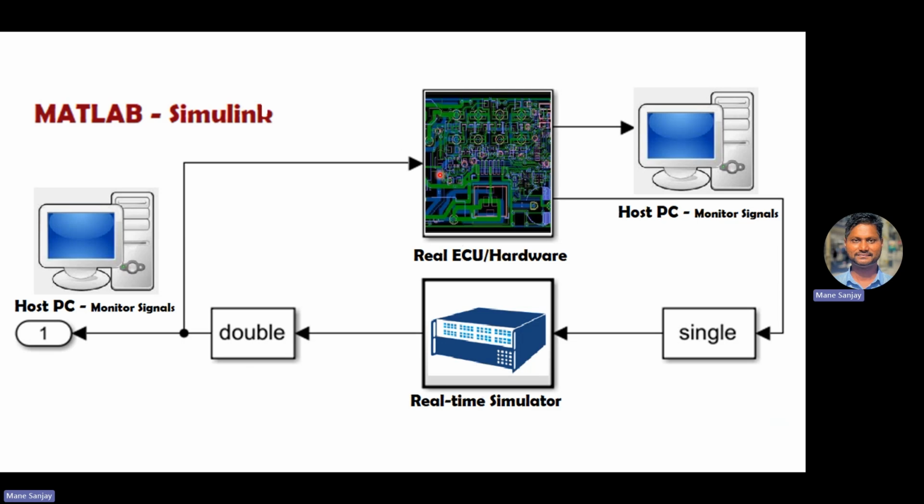When it comes to checking the entire logic which is written inside any of the ECU, then we usually use the model in loop simulation technique. And when it comes to real-time performance, we usually prefer the hardware in loop simulation. This method is basically used before production of that specific component. In terms of fidelity, HIL is very high fidelity, very accurate in giving the real-time behavior of the performance of the ECU or the model which we are simulating here.